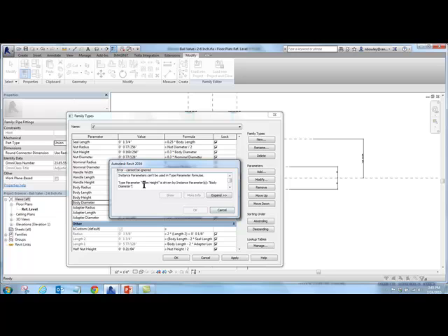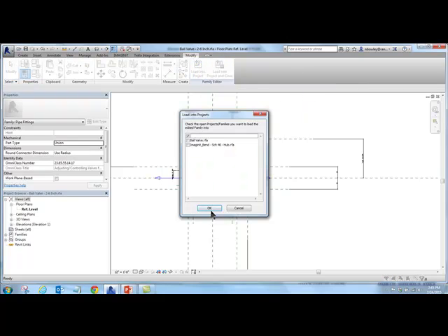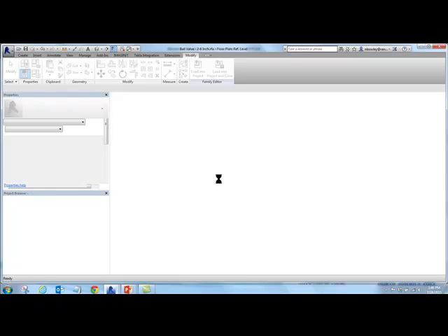And it says stem height is being driven by this instance parameter. So then you've got to kind of reverse engineer it, and oh, now I've got to go fix stem height and body diameter first, and then I can go fix the one that I just clicked on. Again, that's going to take too much time. But just by making this a fitting and then doing those, I would then be able to change pipe sizes.